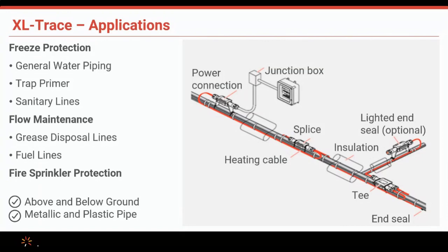Flow maintenance. Anytime you're looking at maintaining a higher temperature, greasy waste is an example. We like to design and maintain for 110 degrees versus freeze protection, which would just be at 40. So that makes a big difference in how many watts per foot is required.